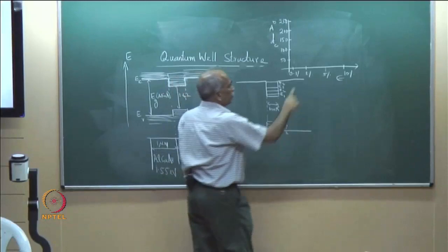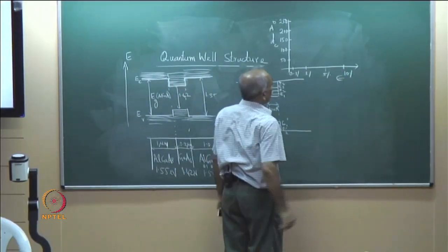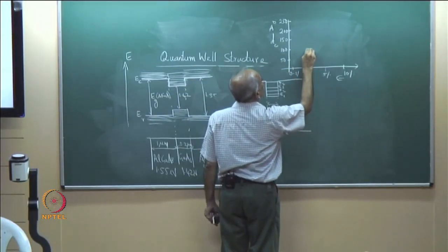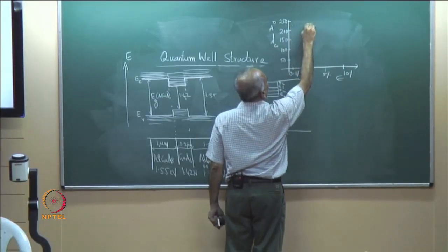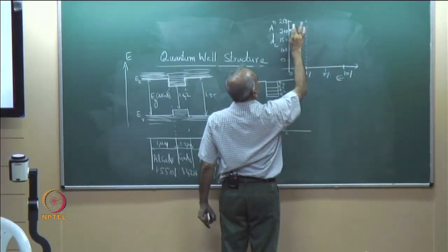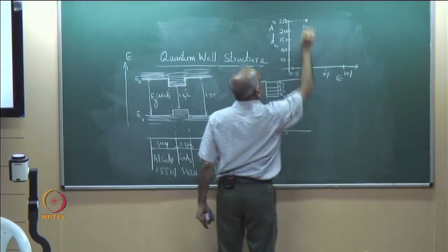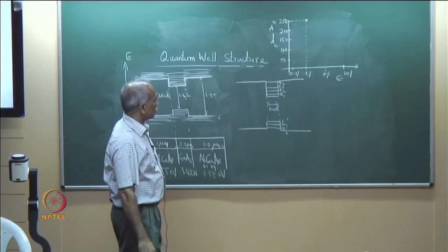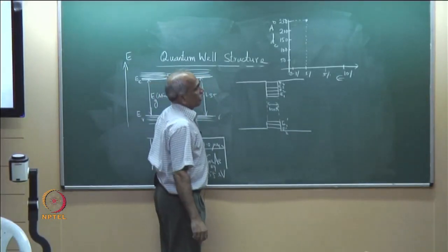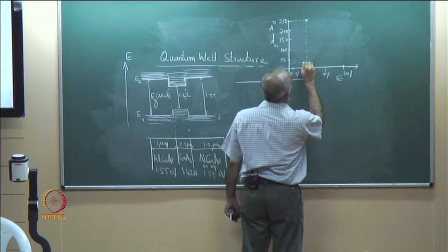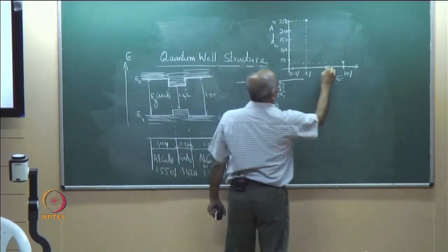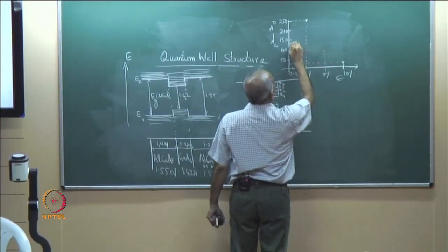I had calculated already for 1% and 10%. For 1% it was 250 angstroms. I had taken an example just now with a_s equal to 5 angstrom. So, you saw this is dc, the critical thickness was 250 angstrom here. For 1% 250, is it? Please check. 250 angstrom, and for 10% we had 25 angstrom. For 5% you will have 125 angstrom.